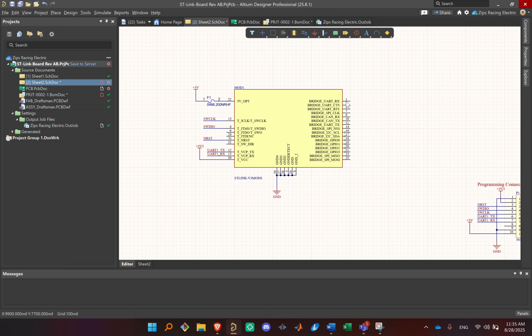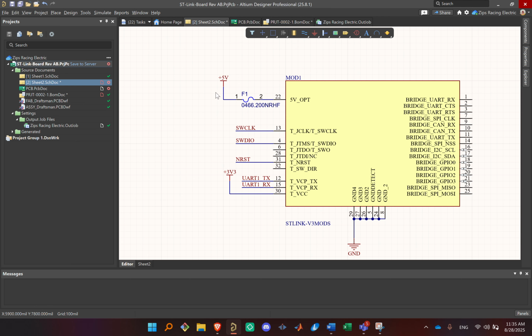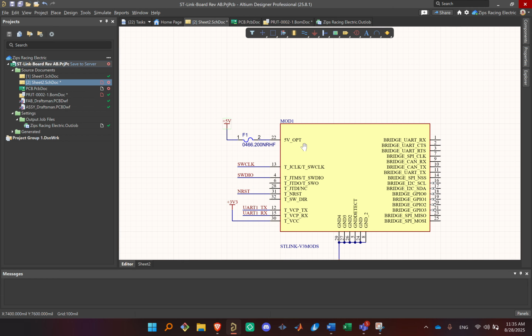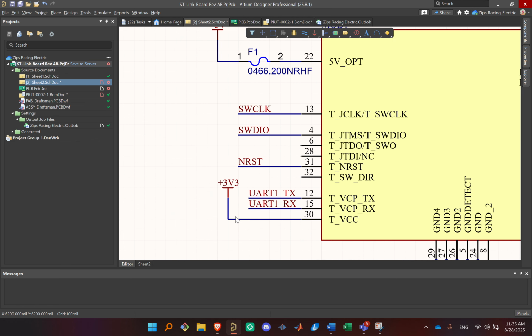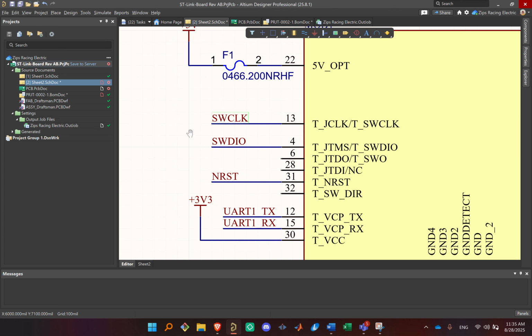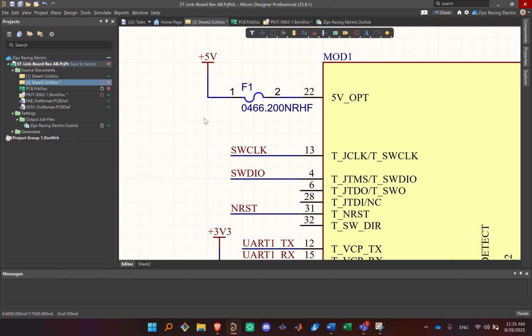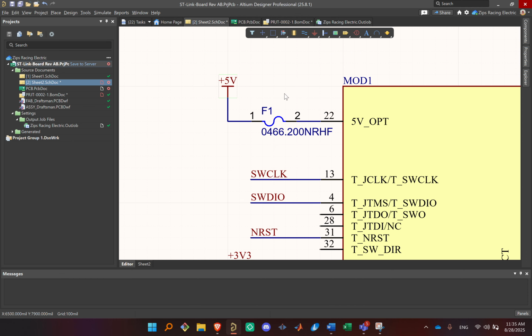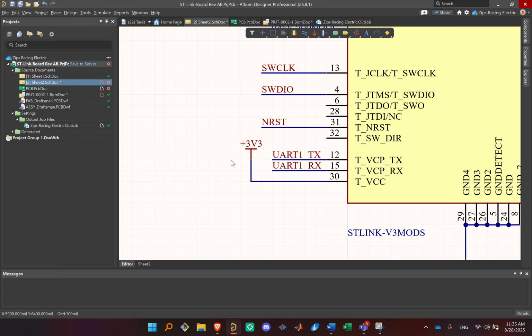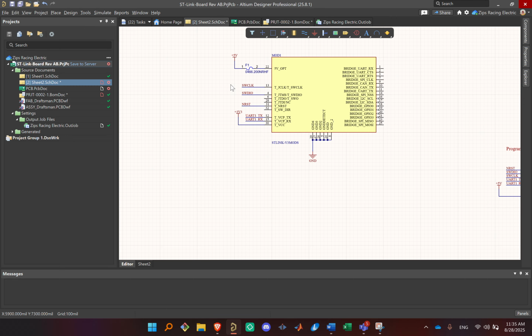So, going back into Altium here, I want to show some of the symbols that you're going to be interacting with a lot. First of all is going to be your power rails. Power rails in Altium are what you'd call a unique net. A net is basically any electrical signal with some name ascribed to it. Like right here, it's SWCLK for the clock. And here we can see our power port. That's a 5-volt power rail. And then down here, we have a 3-volt power rail.